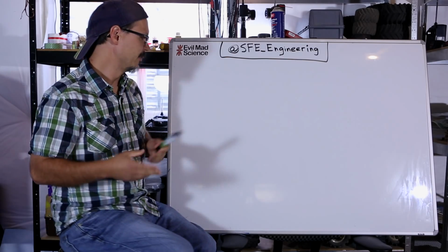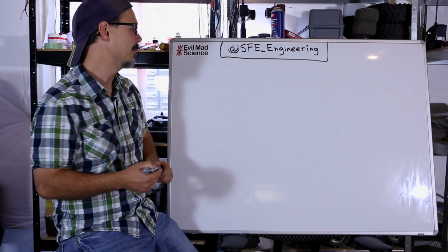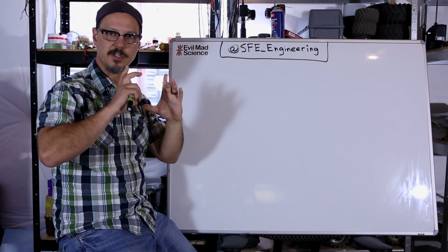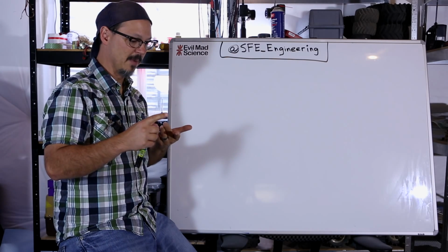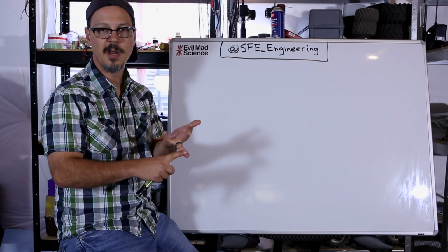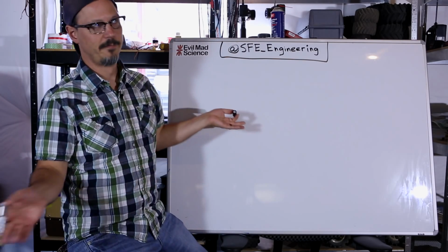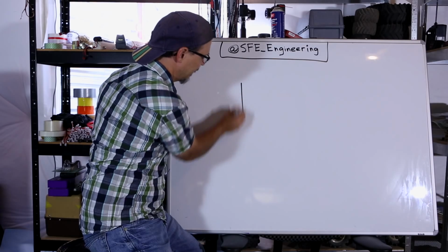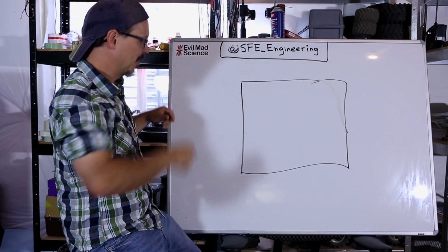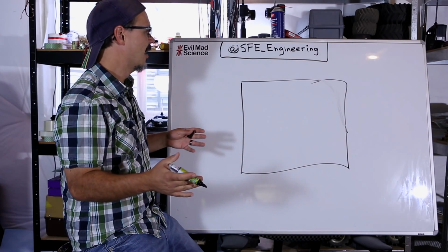mechanical prerequisites. So for example, is there a shape that the board has to be in? I mean, if you've got it fitting into a specific enclosure, that shape is going to be a constraining factor. The mechanical components, like a potentiometer or a switch or a jack of some kind, where do those have to be? So for example, I'm just going to assume that I'm putting it into a square box. Hey, it looks like this. That's not a square, Pete. So for example, you start to think about, okay, well, how am I going to use this? You've got to start thinking about that.